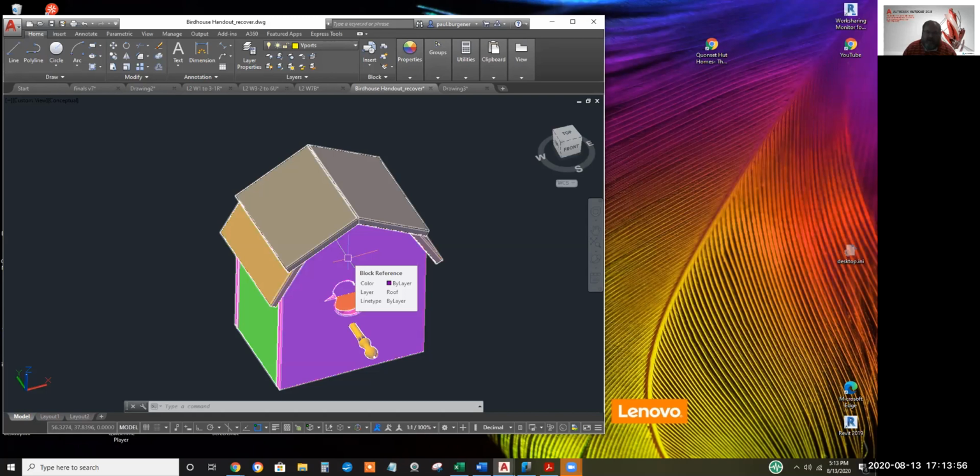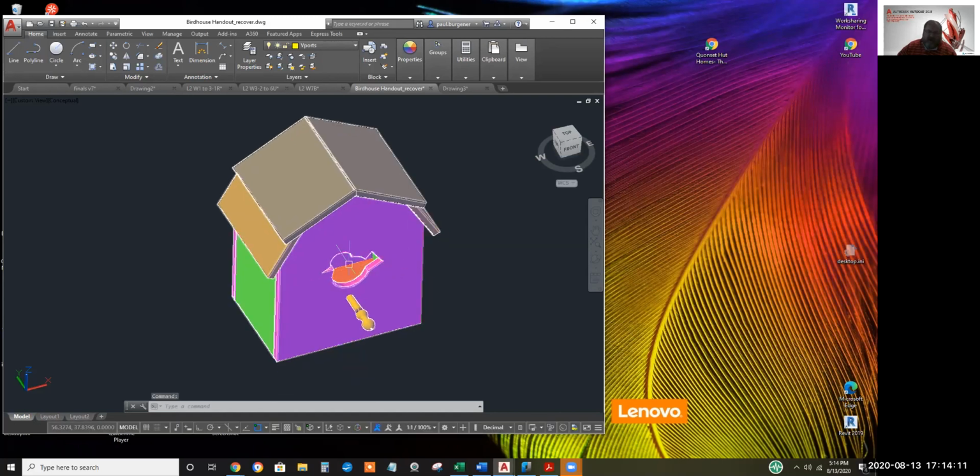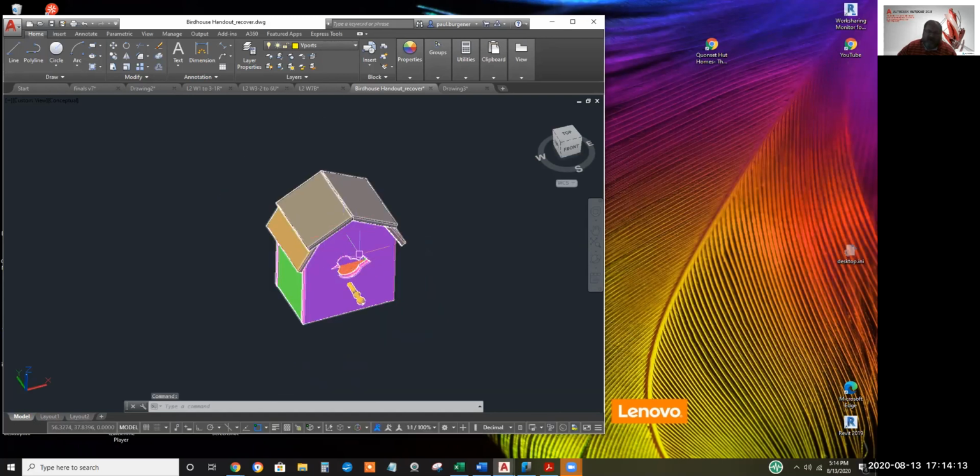For a single solid, it's doable. I don't know if for this assembly we could get center of gravity. Now, AutoCAD's smart enough to know the XYZ of this object, and with that, and maybe the weight typed in, you can do list and trim calculations with attributes.